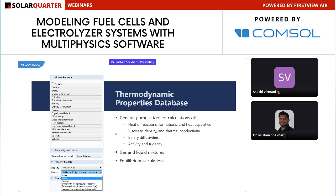So if I just list what kind of properties are required prior to going for the simulation, you just need to know the porosities and the electrode densities for the particular electrode that you have chosen, and that is good enough data for this particular fuel cell simulation in COMSOL.